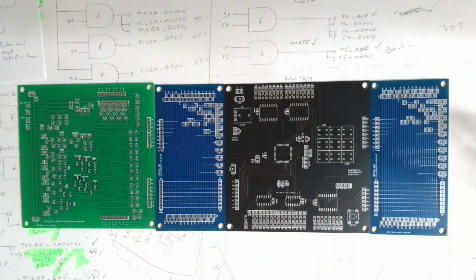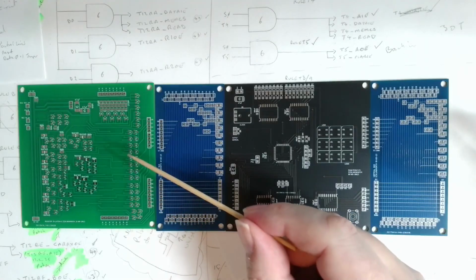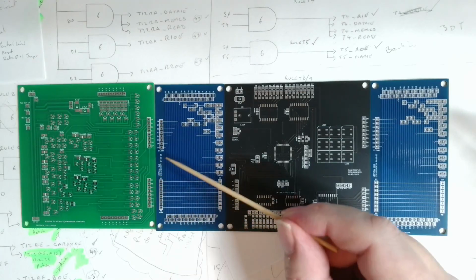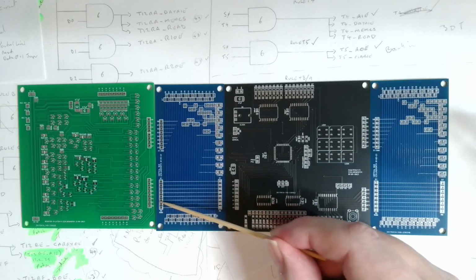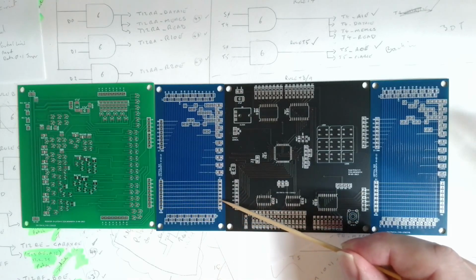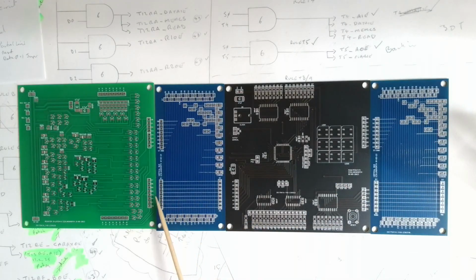Here we have the circuit board for the motherboard, the one in black. On the left here, we've got a green general register. This is the memory address register. So output from here will be the actual address bus, which will jump across this card here. This is how they're laid out on the actual CPU. So these links come straight across and put the address into the motherboard.